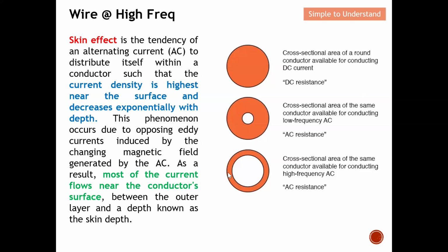So basically, this is the effect. Under almost 0 hertz, when we increase the frequency slightly, still considered low frequency, and then we further increase the frequency to high frequency, this is the skin effect. We classify this, so I want to highlight this. Skin effect is in this orange zone. When we increase the frequency, you can see that the skin depth becomes smaller. So this is the effect of skin effect at high frequency.